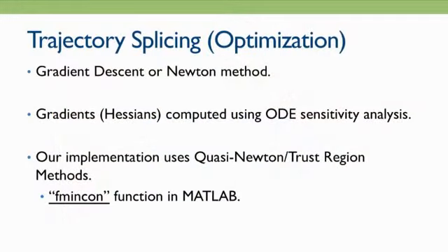It insists on recompiling the model, so it's a technical issue that we just have. Every time we do it, the model compiles again, so that makes it very hard for us to make this worthwhile. Otherwise, the simulation itself just swamps up all the cost of doing work for us. So that becomes harder, and computing these gradients and Hessians in Simulink Stateflow still requires some support, which they aren't providing yet, but there is some hope that they will provide it soon enough.